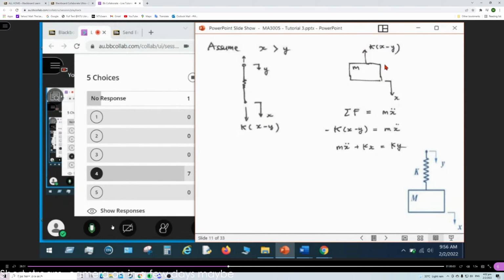Some would say one force cannot get balance, but here we do not consider balance. Why? This is not static force analysis. This is dynamic force analysis, dynamic system analysis. So one force, the summation of all the forces, only one. Assuming this direction is negative and this direction positive, negative equals ma. According to Newton's second law, this is allowed.